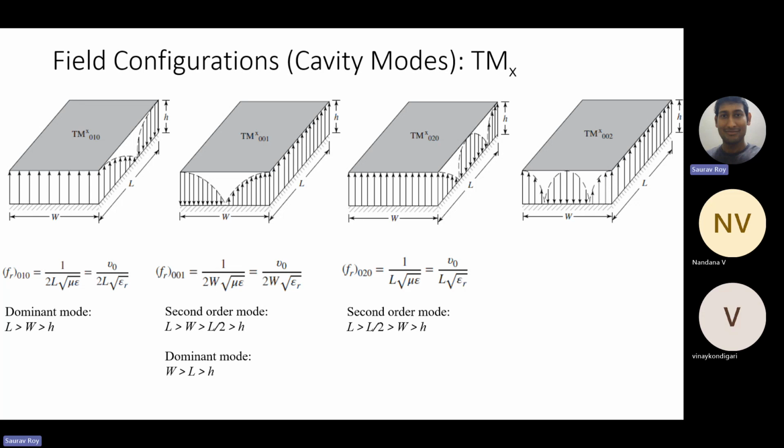So this is for our antenna. But generally, in a waveguide, if you need any particular mode, like TE10 or TE01 mode, you have to excite it in that particular configuration. You must remember that we use defined kinds of pins, coaxial conductor pins, or bent pins to excite these modes. So you need a particular kind of excitation to excite a particular mode. But here, it will depend more on the frequency band of your excitation.